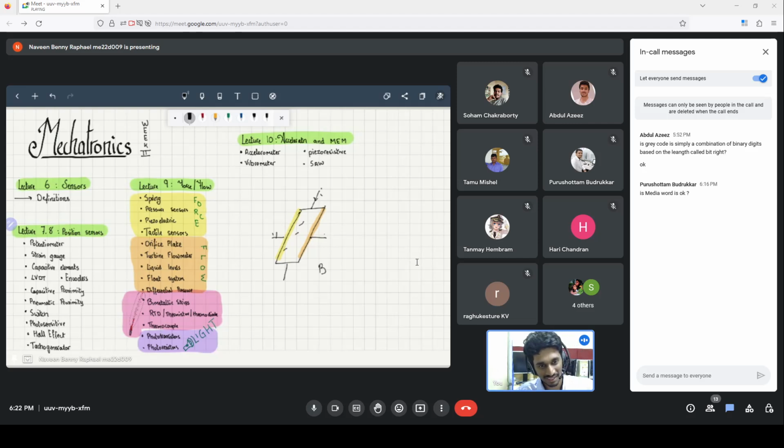Yeah, so we saw there are different kinds of flow measurements. There's the orifice plate. There's the turbine flow meter, which has a very nice diagram. Because of the Bernoulli equation, we know pressure is related to height, and therefore we can also use liquid levels to measure the pressure. The float system is perhaps the simplest solution. Instead of measuring the pressure, we can actually measure the height of the liquid using a float system, and that's a nice solution.